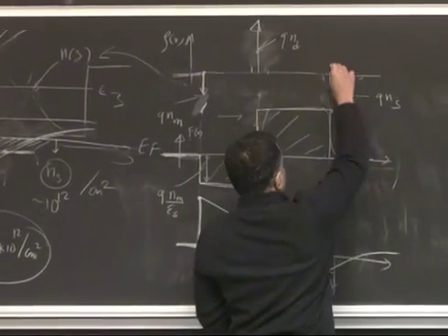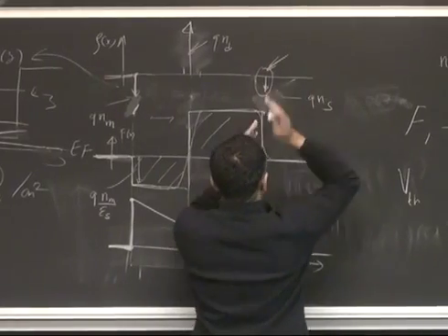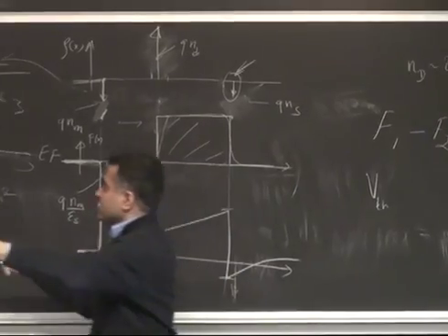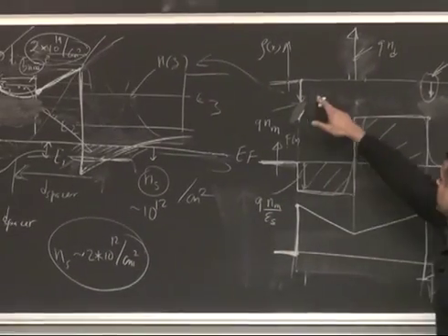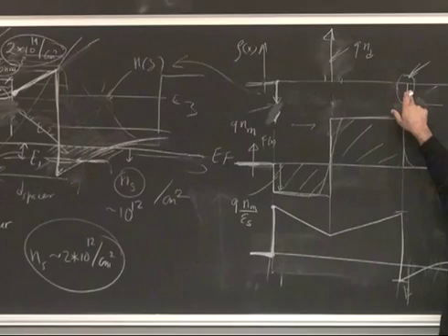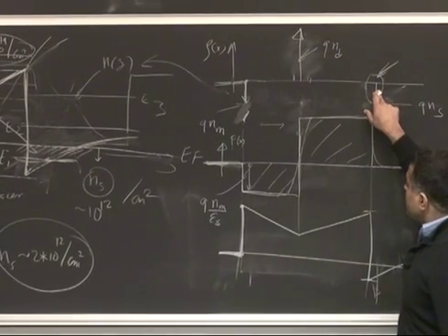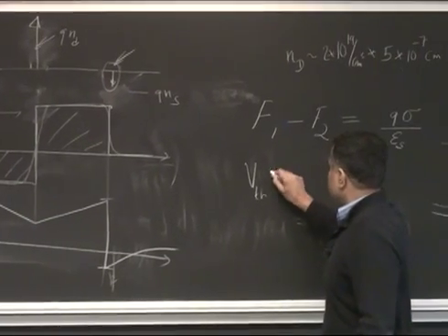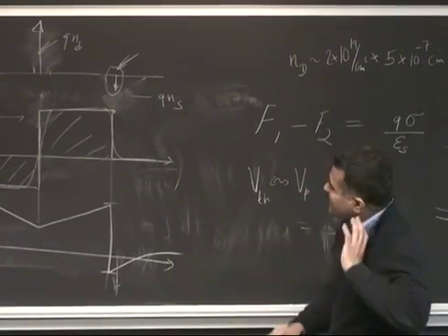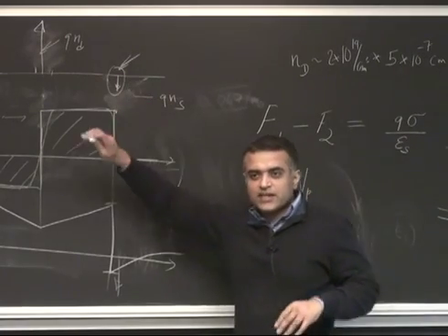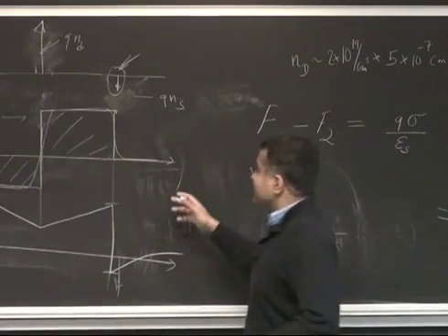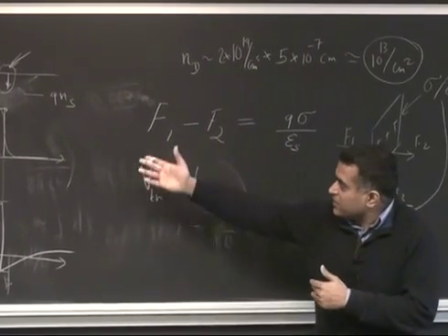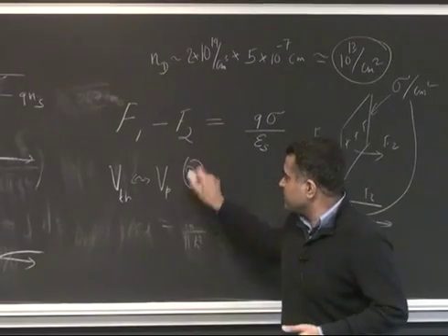So this is a 2D electron gas, and your transistor, for example, will have contacts to this electron gas across this junction, one on this side, the other, the source and the drain, and then the gate is trying to control this charge. Now, one of the questions is what is the threshold voltage, or sometimes also called the pinch-off voltage, at which there is no charge left here. And that's in quotes when I say no charge left. We'll see that there is more to that story. What is the pinch-off voltage of this device?